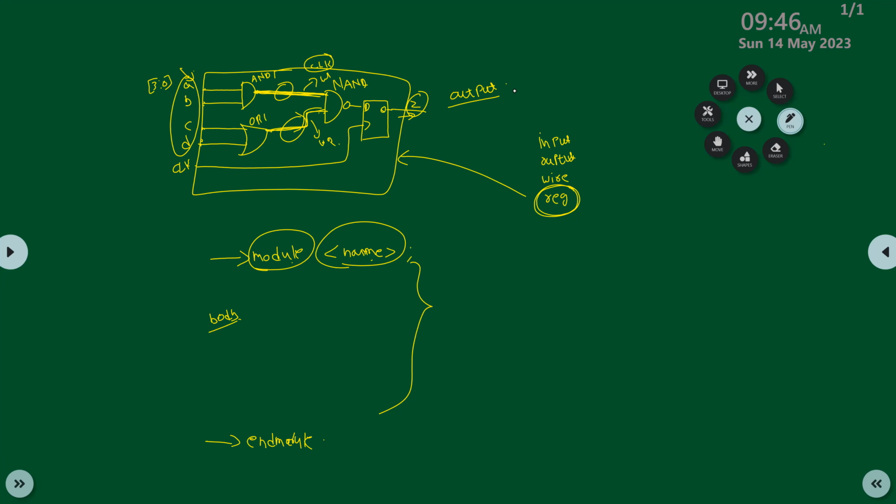Okay, you can declare Z as output along with reg also, because whatever the outputs which are coming from the flip-flop, those you need to declare as registers. If the flip-flop is present internally, say after the AND gates you have the register with D, Q, clock, and this output is given to a NAND gate. The other input of the NAND gate might be a direct OR operation. Let's say A, B, C, D, and this is clock, this is the flop, and these are the gates.